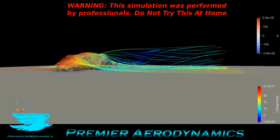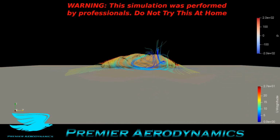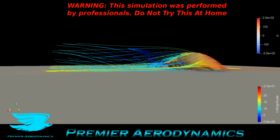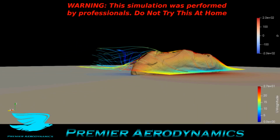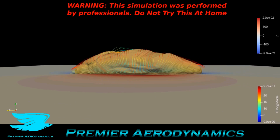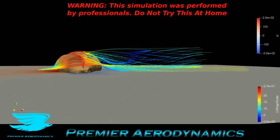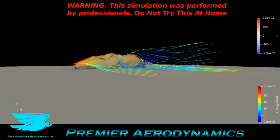Now we have the streamlines going around the loaf of bread, and we have the ground plane visible as well with the pressure plotted. First of all, we can see that the pressure in front of the loaf of bread is quite high, as you'd expect. As the flow hits the front of the loaf of bread, it has to decelerate. That increases the pressure. Around the edges, when you have a lot of flow separation, the pressure drops a lot.